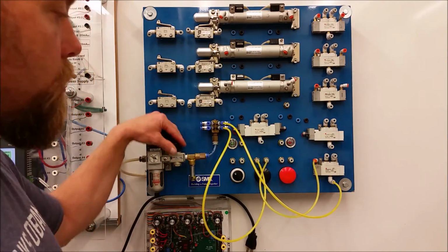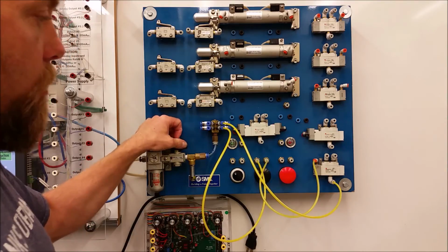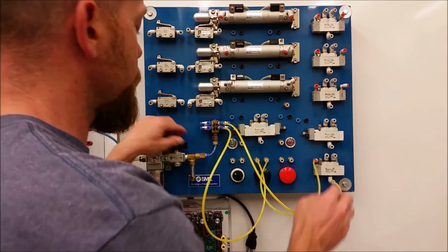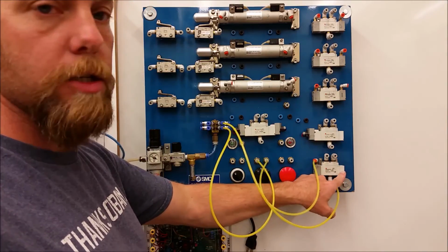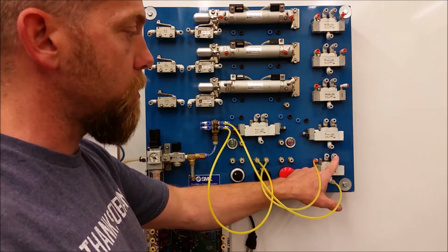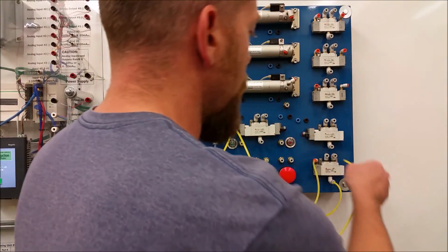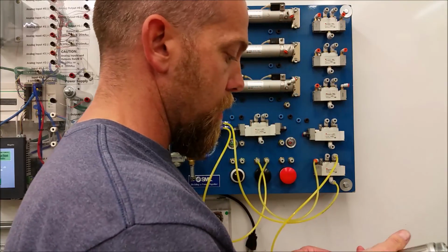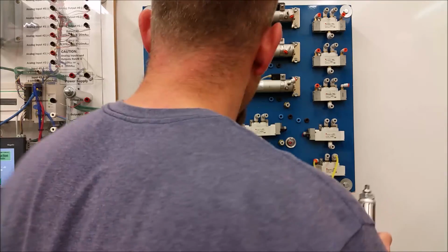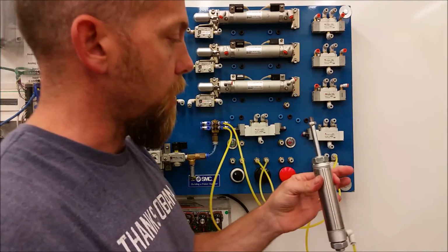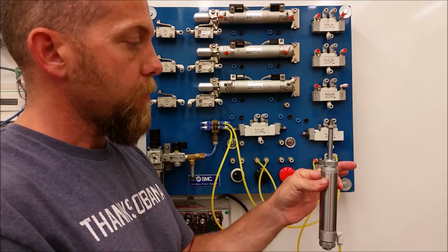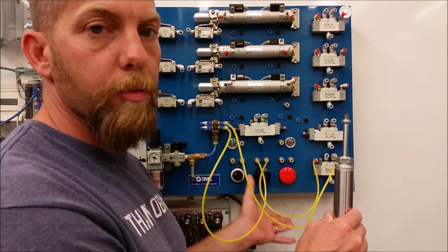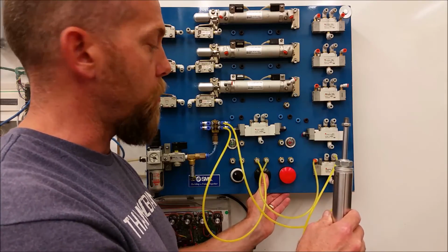And I need this one to do the opposite output. So when I press this push button, I need the air, let's see, the air's coming out of there at rest, right? Because the spring is having that air go from 1 to 2. So I need the opposite output of what we had before. I need to have that single acting cylinder extend as soon as I turn on the air. Okay, so we've got this, and now when we press the push button, we need it to retract, doing the opposite, or inverting the signal of what we had before.